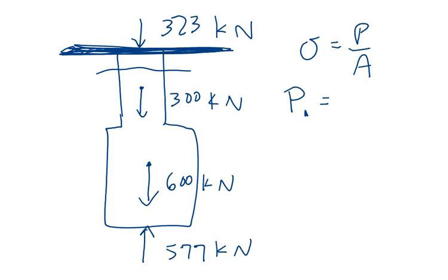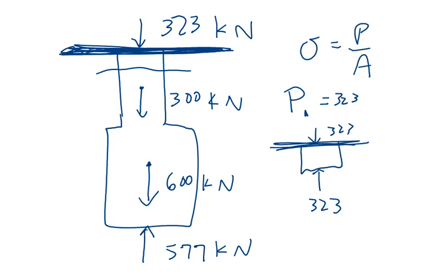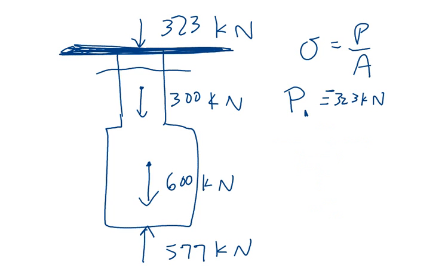It's, well, if you make that cut, right, there's the 323, and then I make that cut. I must have 323 up. What is that? That's compression, right? Can everybody see? If this top is my reference, and then I push against that, then that's compression. So it's 323 kilonewtons negative. Okay? How do I find the internal force in the second segment?